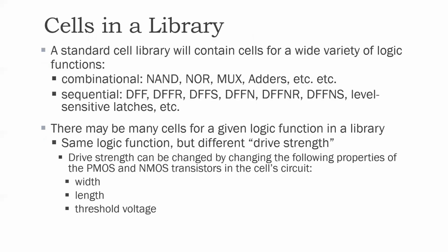The cells in a library. A standard cell library will contain cells for a wide variety of logic functions. So you would have a variety of combination functions, as I said, NAND, NOR, MUX, adders, etc. Then there will also be various sequential functions. Usually they're all different flavors of a D flip-flop.